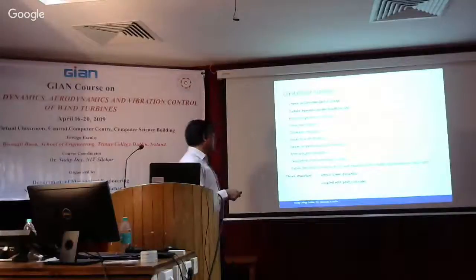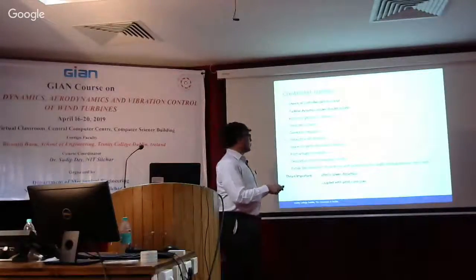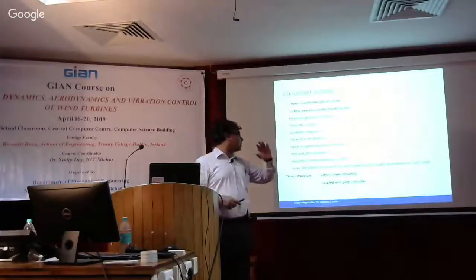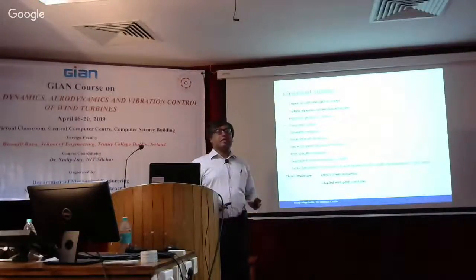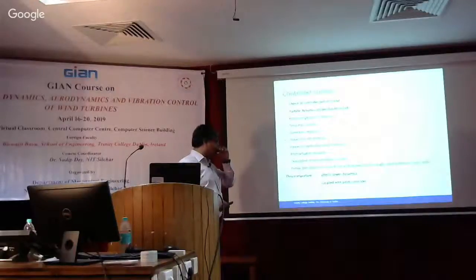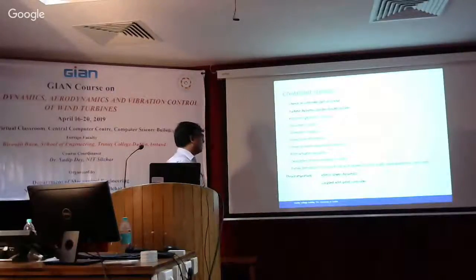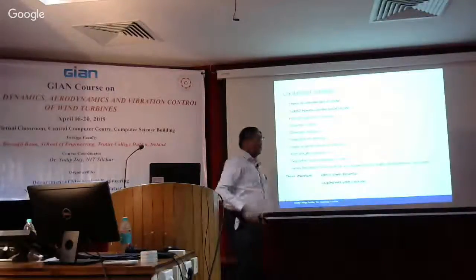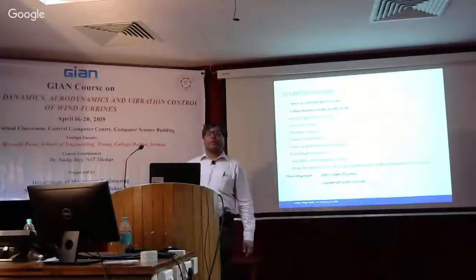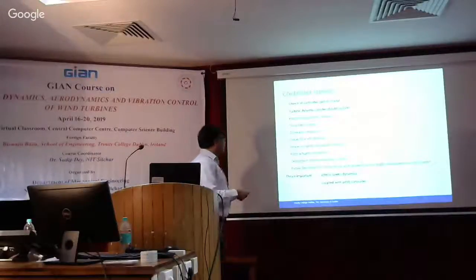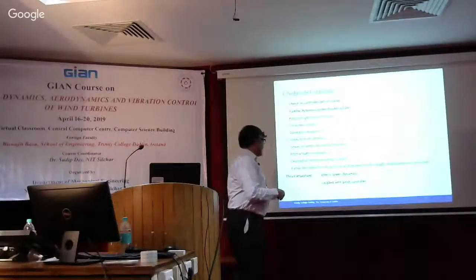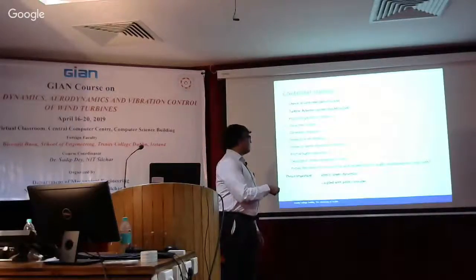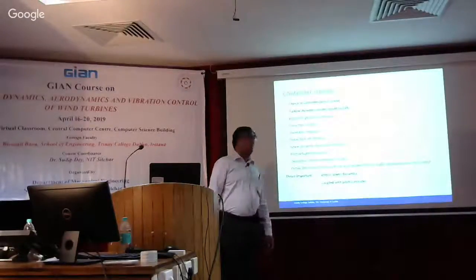So obviously, we need to know the derivative of the torque with respect to pitch angle. How much is the torque going to change if the pitch angle is changed? How much is the torque going to change if the wind speed is changed? Same with the generator speed as well. These are things, and some of them we haven't discussed, because as I said, they are more advanced in terms of control. But thrust is an important aspect, and we have considered that, and we will go into a little more detail with the tower dynamics coupled with the pitch controller.